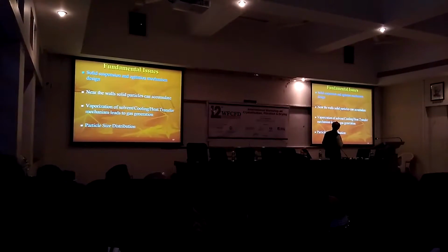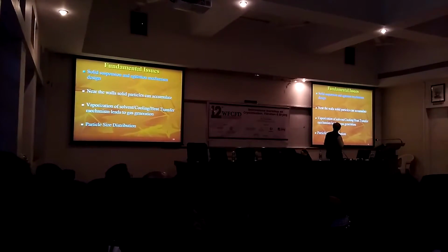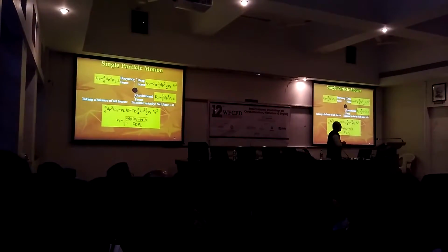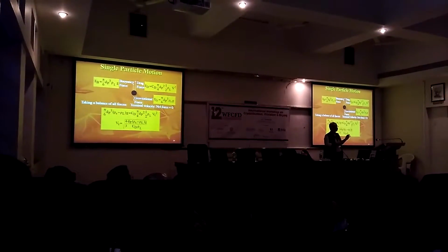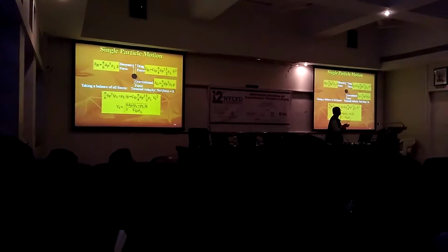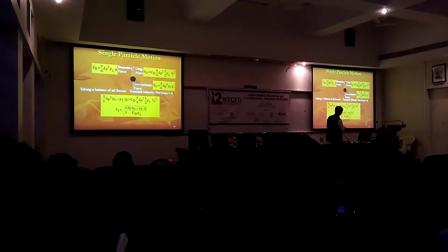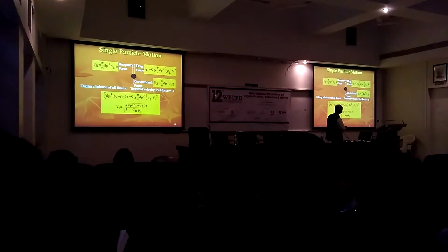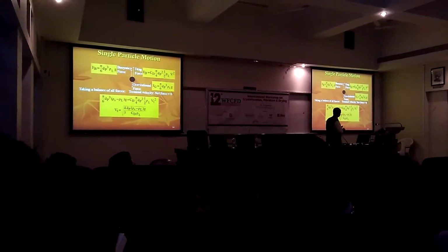So let us focus our attention to solid suspension. And as chemical engineers, you know solid suspension can be achieved if you create forces in the upward direction which overcome the forces which are related to buoyancy and drag forces and the gravitational forces which is going to make the particle settle. So that gives you a simple correlation depending upon, of course, the Reynolds number of the particles.